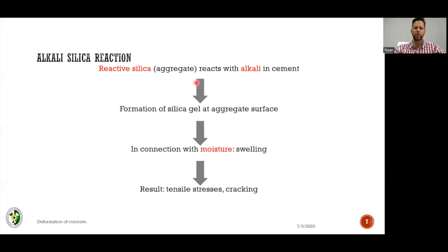So some of these quarries have reactive silica aggregates, and they were used in these bridges. And the only way that the client could then say, okay, let's try and mitigate the damage, was to say, let's try and avoid moisture. So they were painting the bridges, sealing them with a surface-applied water sealant or a waterproofing agent. Now, whether this was cementitious, I'm assuming it would have been cementitious, I don't think it would be an epoxy base, but it could be either of those. They were trying to limit any further ingress of water.